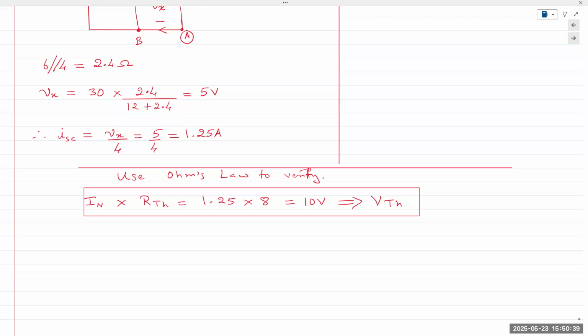You can also see the downside of using Ohm's law to find a quantity directly. Let's say your calculation for RTH was incorrect, perhaps, or VTH was incorrect. So if we don't determine Norton current and we take the incorrect value for RTH or VTH and we apply Ohm's law, well, now instead of one incorrect value, we have two incorrect answers.